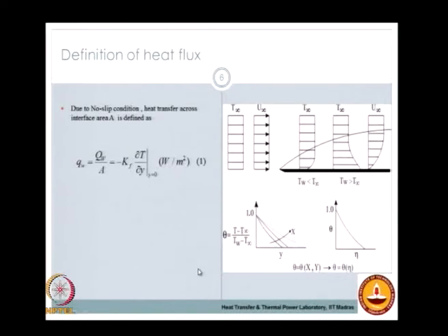The good thing about this flat plate boundary layer problem is that it is very interesting and more fundamental when you develop what we call similarity solutions. If you define a non-dimensional temperature theta and plot that, you will find this non-dimensional temperature is a function of both the x coordinate, your axial distance along the plate, as well as the y coordinate, or the height across the plate.